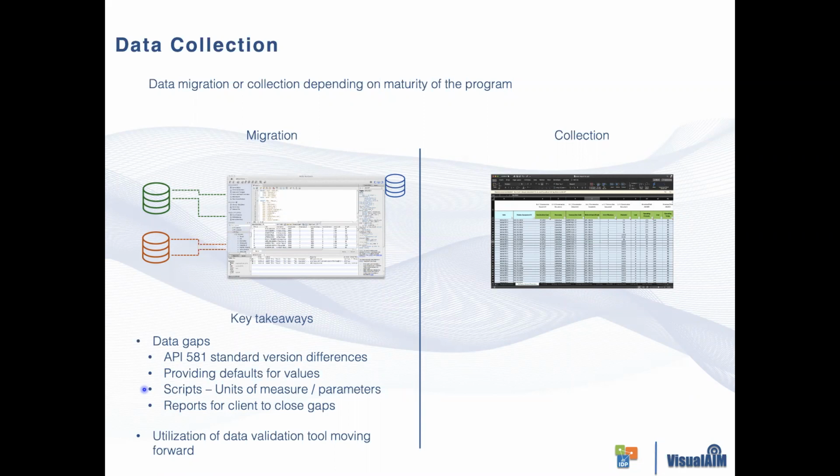In the parameters for design temperature, if you have 100 degrees Fahrenheit for the design temperature of a particular asset, and the operating temperature comes in as 150 degrees Fahrenheit, we have scripts and special codes that tell us it's flagging the fact that you're putting an operating temperature that's higher than your design temperature. This is flagged and sent back for review to the customer.